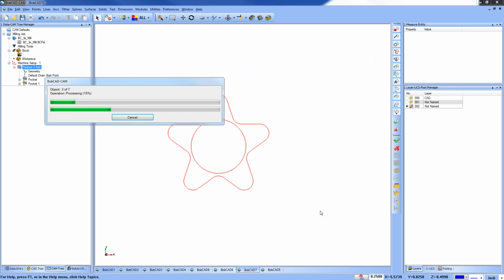So that's the nice thing about the adaptive toolpath: you can work from the outside in. It could be one-sided open, it could be two-sided open, it could be three-sided open, it could be four-sided open, or you could work from the inside out. So it's just a really very dynamic feature that you can use in a lot of different ways.